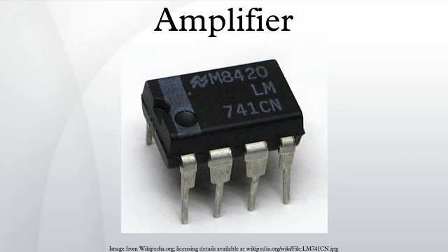A Class D amplifier uses some form of pulse width modulation to control the output devices. The conduction angle of each device is no longer related directly to the input signal but instead varies in pulse width. These are sometimes called digital amplifiers because the output device is switched fully on or off, and not carrying current proportional to the signal amplitude.